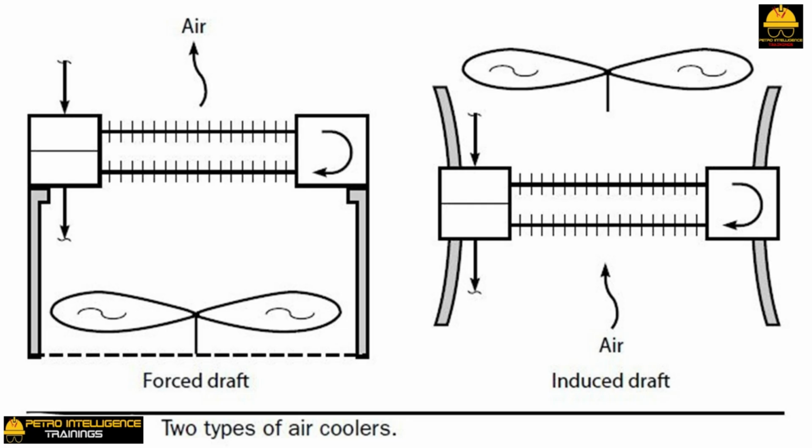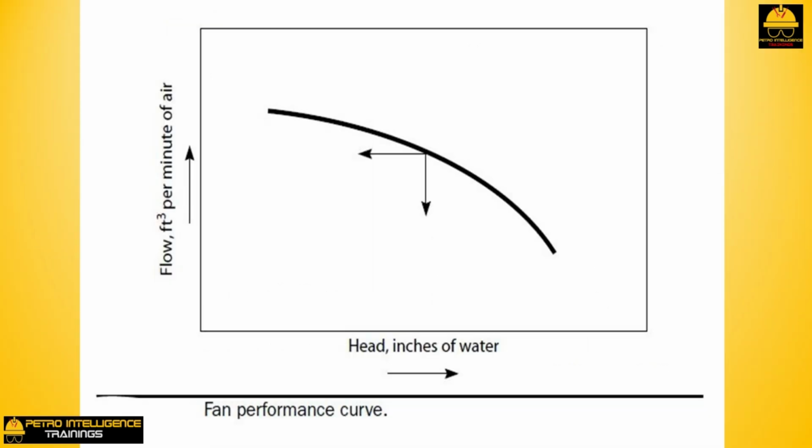As the tube bundle fouls, the air pressure to the fan drops. The air pressure from the discharge of the fan is just atmospheric pressure. It remains constant. The waterhead, in inches, developed by the fan increases. The flow of air through the fan and the bundle decreases. This is consistent with picture. The amp load on the motor spinning the fan decreases.